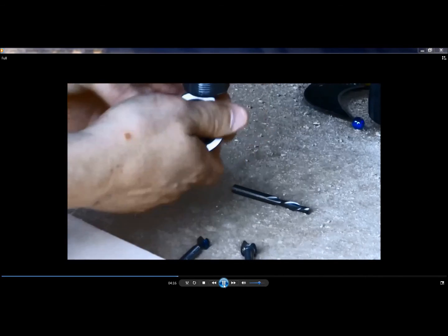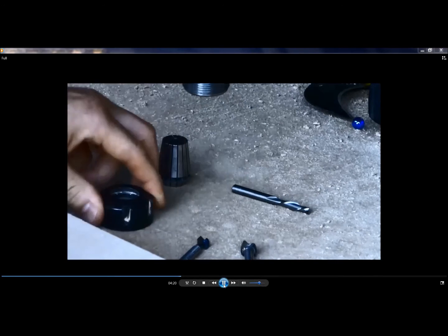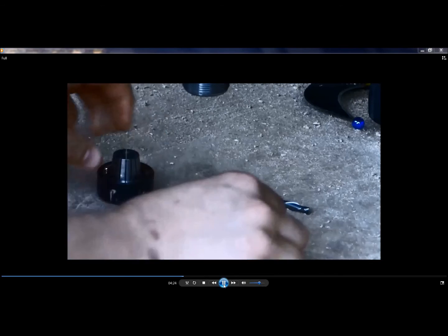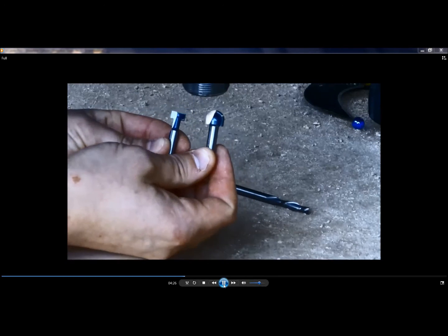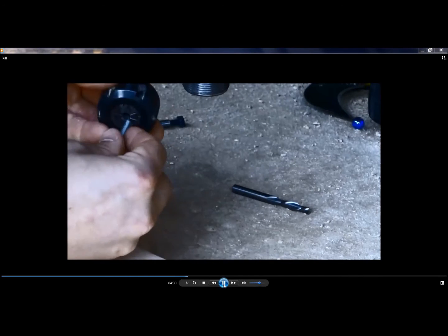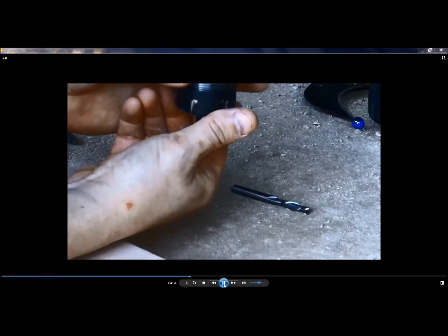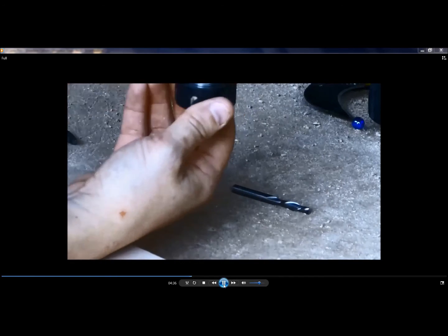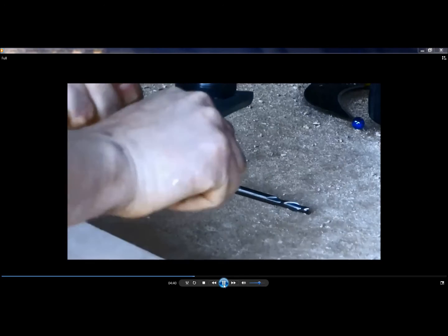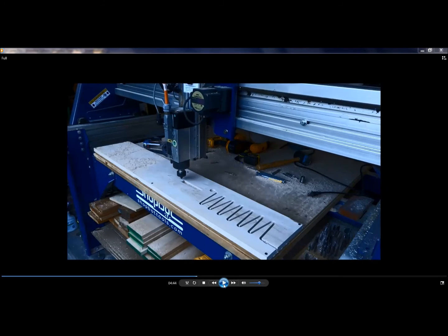I took my straight bit out. Every time you take these bits apart, pull those apart, knock the sawdust out, push them back together, make sure they're whole. This one now I'm going to try with a round over bit, and hopefully that'll keep the marble in track a little bit more. And if those threads aren't going nice and easily, don't over tighten them. You don't want to strip the threads out on your spindle. And then get this guy zeroed, and you're ready to now make that cut.